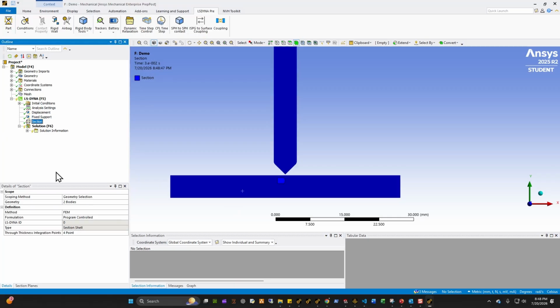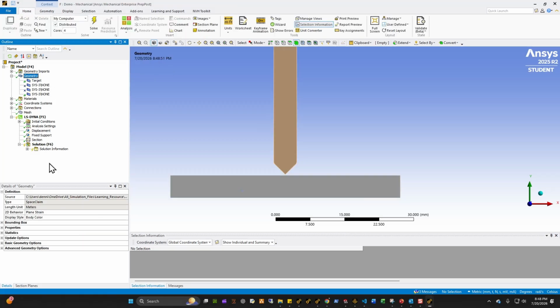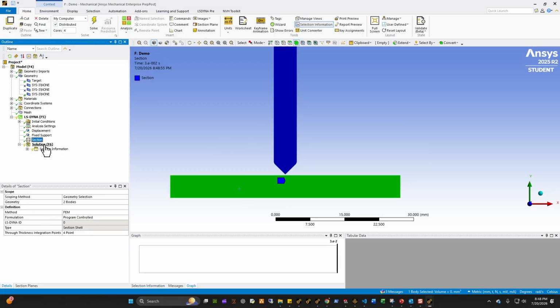Like I said, this thing right here, you can't really change it. It doesn't give you any option. By changing here to plane strain, you automatically change the section of this part and this part to 13, alpha 13, which is what you're looking for.